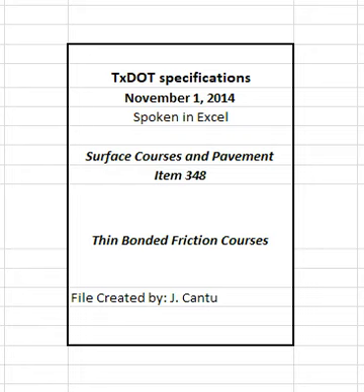4.4.2.2.5 Testing the trial batch. The engineer will sample and test the trial batch within 1 full working day to ensure that the mixture meets the requirements in Table 8. The engineer will have the option to perform the following tests on the trial batch. TxDOT 235F, to verify that drain down meets the requirements shown in Table 8. TxDOT 530C, to retain and use for comparison purposes during production, and TxDOT 245F, to verify the Cantabro loss meets the requirement shown in Table 8.